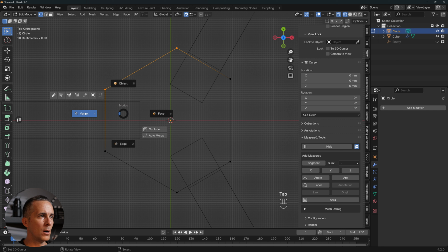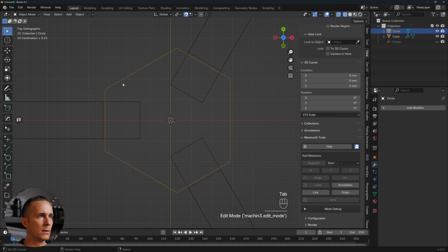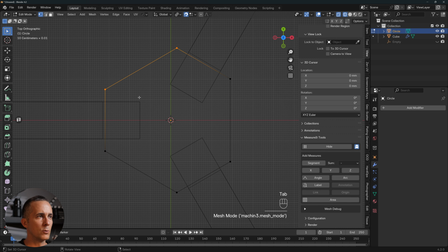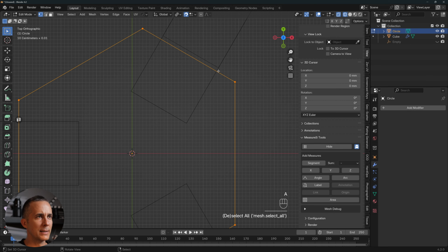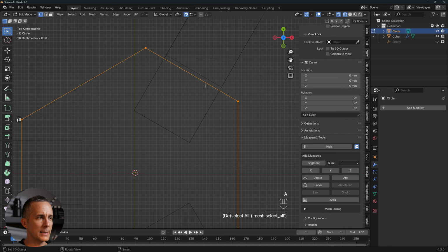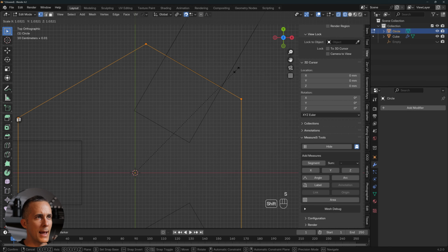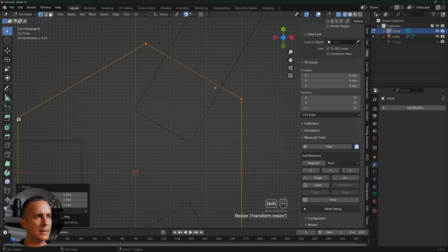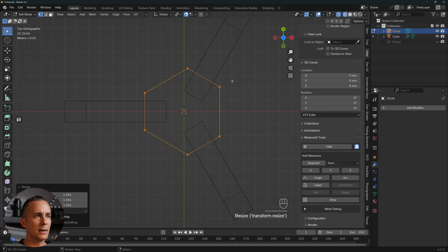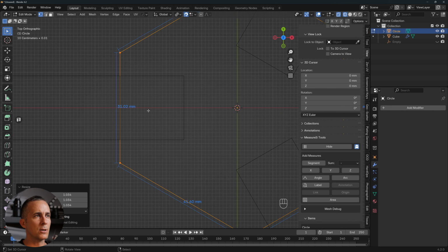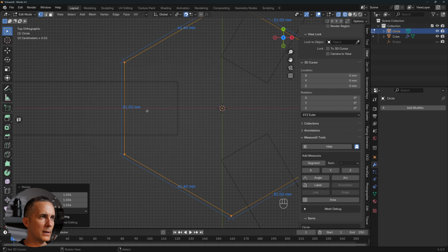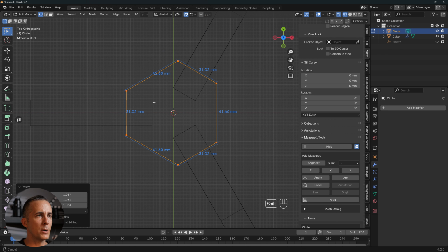I want to go to the object, okay, and actually let's go to vertices, select all. I want to scale everything until they're touching the end of the legs here, so S, scale, and voila, something like this. So let's check our dimensions here. We can set segment again, 31.2. That's also okay. It's 1 millimeter wider. This is wider, so for me that's okay for the project.